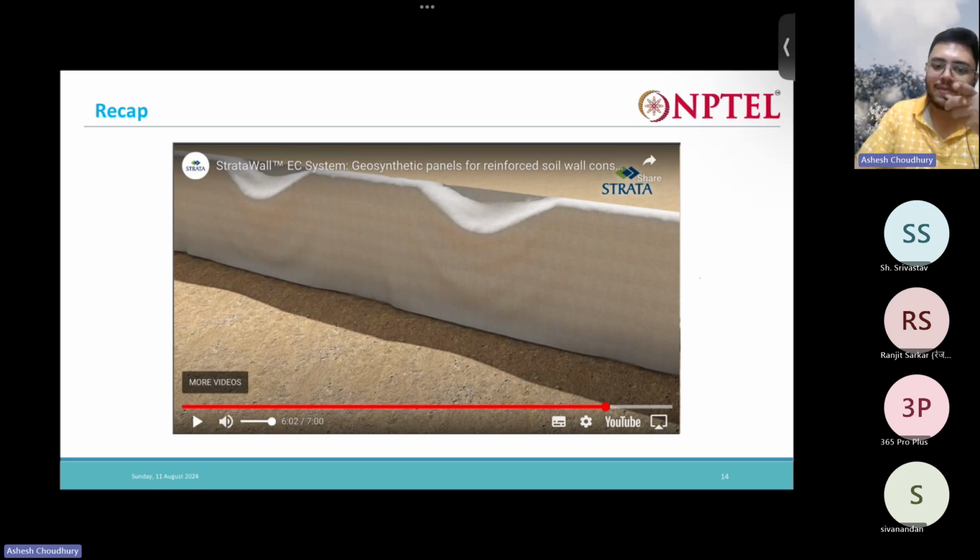Now what is the purpose of this geocomposite? It will allow only the draining of the fluid, and not the fines. Correct. Drainage is the main function of the geocomposite here. Why are we calling it geocomposite? It's the filtration medium. No, why geocomposite? It's made out of two types, non-woven geotextile and... It is called geocomposite because it is made up of two types of geosynthetic.